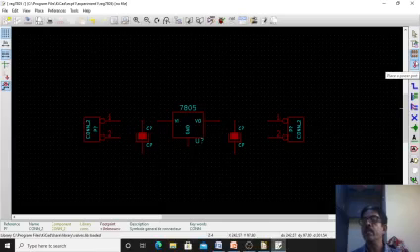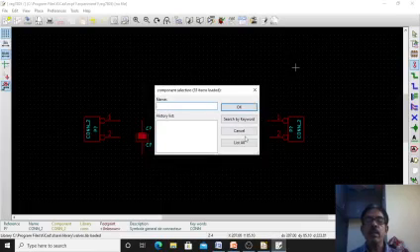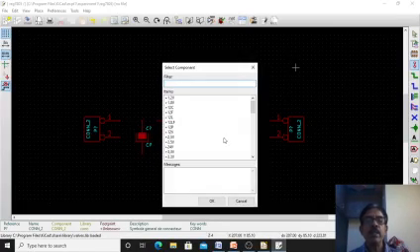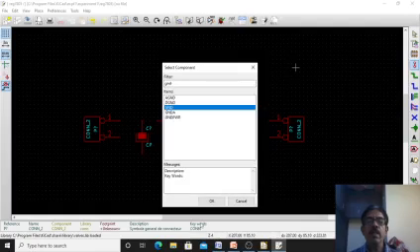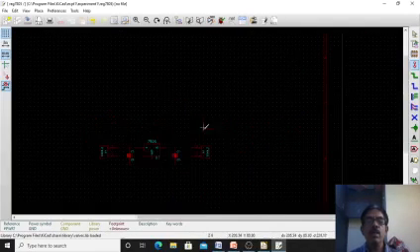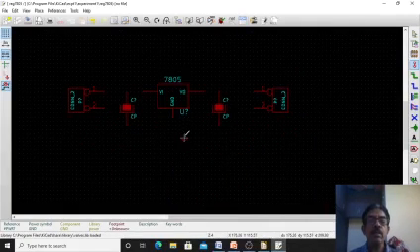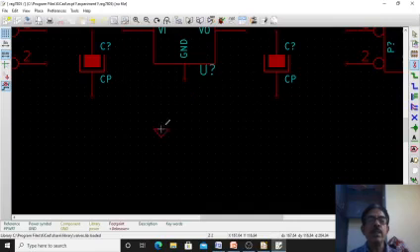It is there here, you can observe it: Place a power port. In this, ground is there. So click here, then you can type it here or use List All. If I type G N D, for example, it will come, or else List All. Then here you can type GND. So here it is. Please take this GND, then say OK. Ground you can place anywhere. For example, I will place it here near.